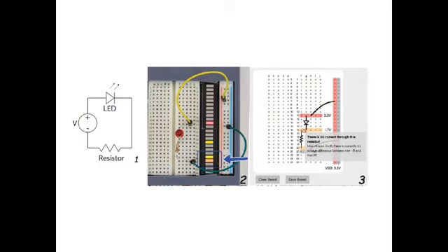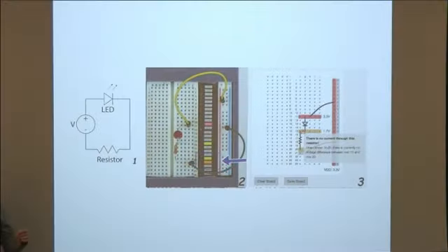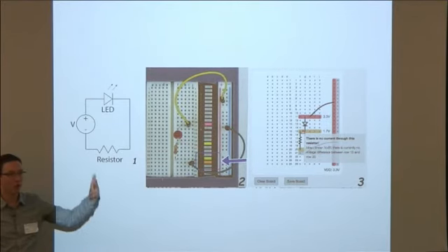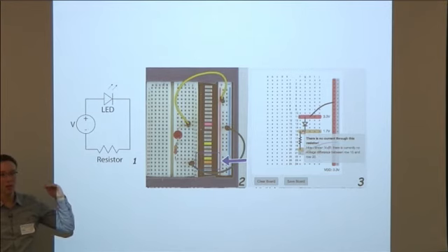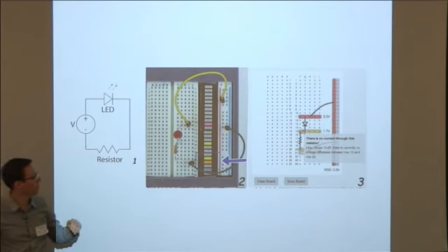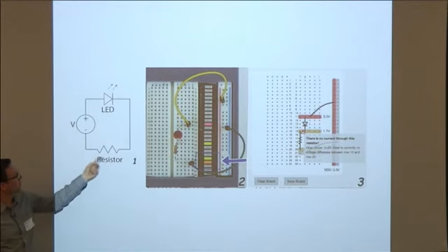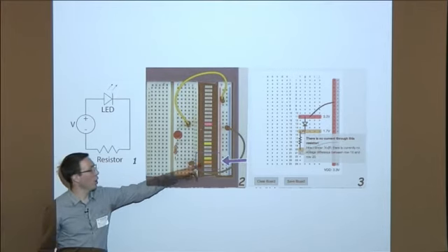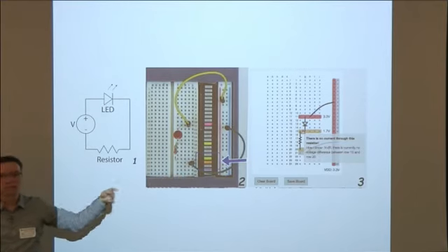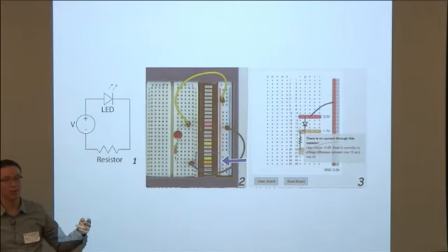And so then what that lets you do is debug all kinds of problems, either through just simple inspection of the voltages or through these smart hints that we layer on top of it. So for example, here, if you connect this circuit, there's a wire that connects the resistor to ground. Well, there should really only be 1 row lit up here. The fact that there are 2 rows lit up tells you that, oh, you probably didn't put the wire into the correct row.